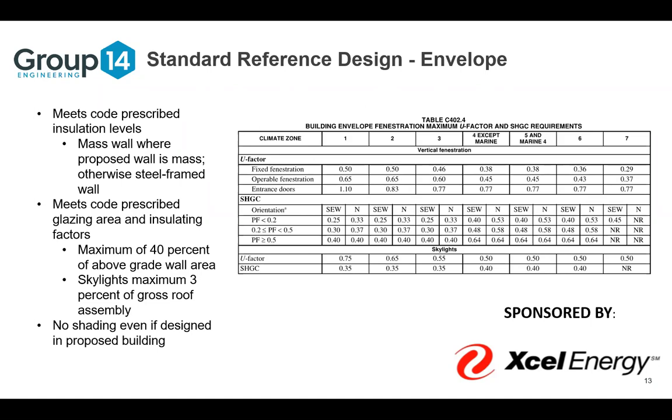Another note here is that within your baseline, you should also be seeing those different solar heat gain coefficients on the southeast and west facades from the north facade. So you want to make sure that they're actually modeling that reduced solar heat gain coefficient glazing on the southeast and west facades. Another note, if you have shading, so permanent shading only, not operable or blinds. So if you have permanent shading in your proposed design, you do not model that shading in your baseline.